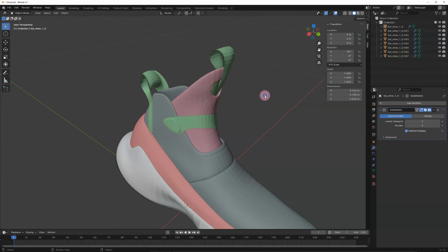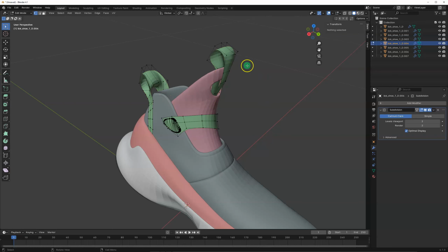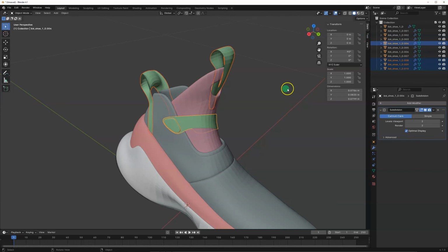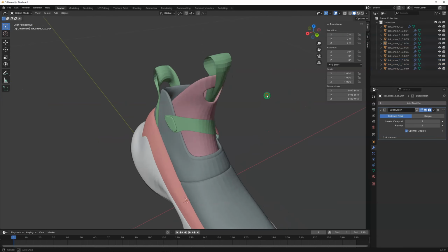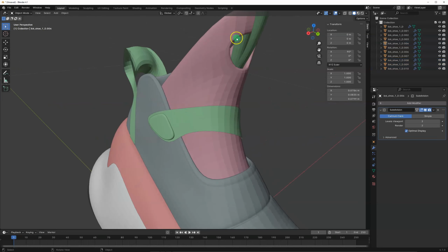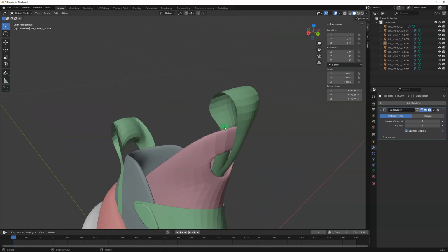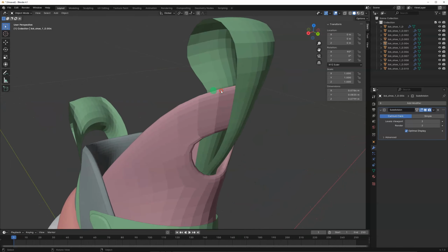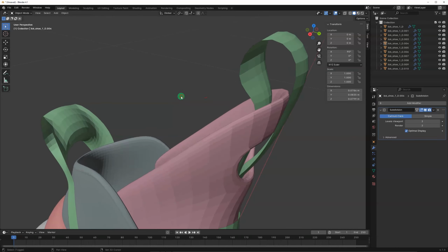So I need to go out of edit mode. I need to select these. Then I need to go into edit mode. Then press P and go by loose parts. And now they're all split. And you can see them here, 4, 8, 9, and 10. So then go Tab. And now we're in object mode. And this is really interesting because this can show you the power of how we want to create our smooth surfaces and our thickened geometries.